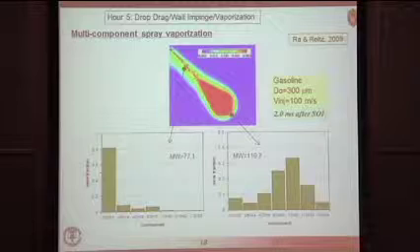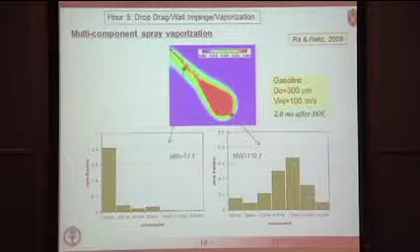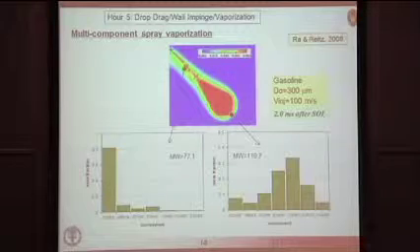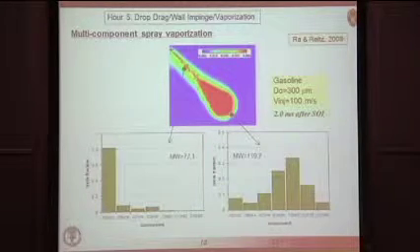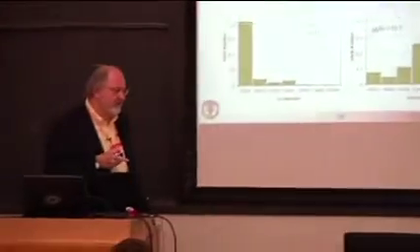How does the D-squared law for the multi-component droplet come in? Okay, so we're not really using the D-squared law. We're using the equations that I showed you for the multi-component. And essentially, as I'm going to show you in a minute, we use a modification of Raoult's law, which essentially says that the concentration of fuel in the vapor phase is related to the concentration in the liquid phase through the vapor pressure. And that's done for each component. So basically, we can actually have some components vaporizing and others condensing on the same drop, depending on the vapor pressure ratios and so on.